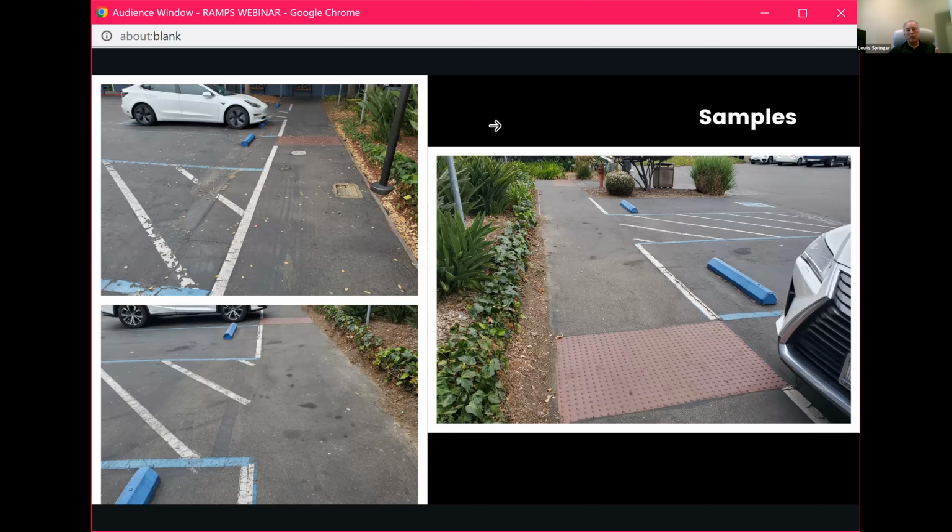Let's see, I think the walkway is 48 inches, so it'd have to be 36 of detectable warning and then 36 inches of walkway. So you'd need 2 more additional feet of walkway instead of putting down a row of bollards or other design solutions that might be available to us as designers. The only solution that's available is that detectable warning.